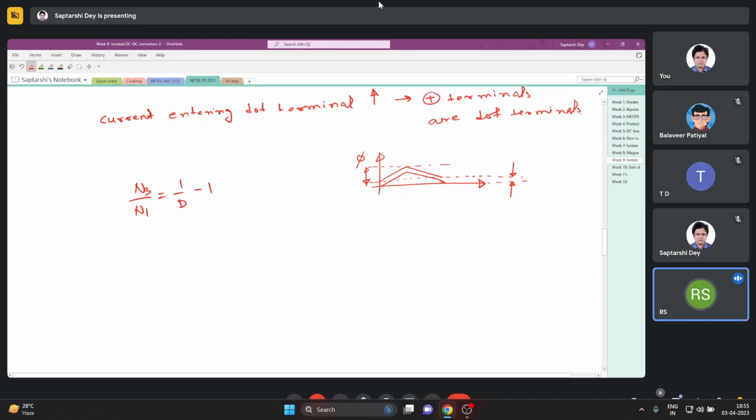So we are saying it stores energy only because it is giving the energy to the load in the next cycle? No, it stores energy because it has an inductance. The transformer of a forward converter also stores energy. But for a flyback converter, we are deliberately keeping a large permeability and a large inductance, because that is what we need. That stored energy is what we are going to supply to the load.